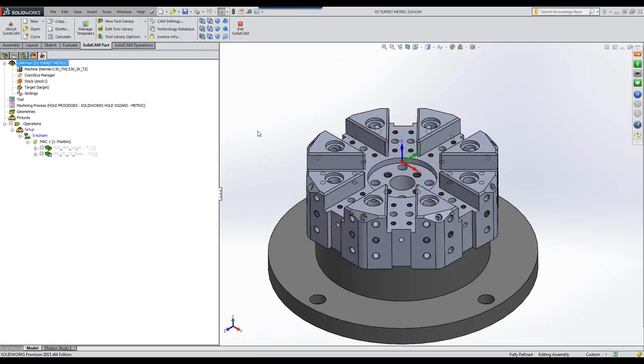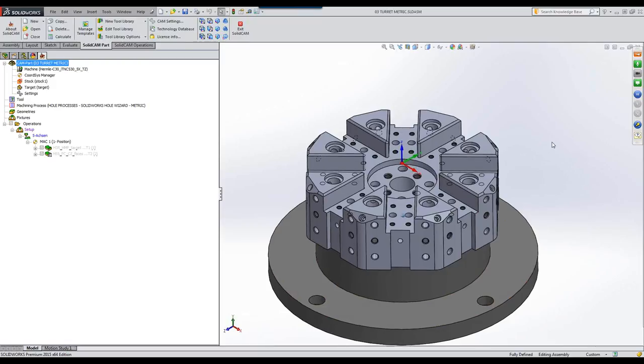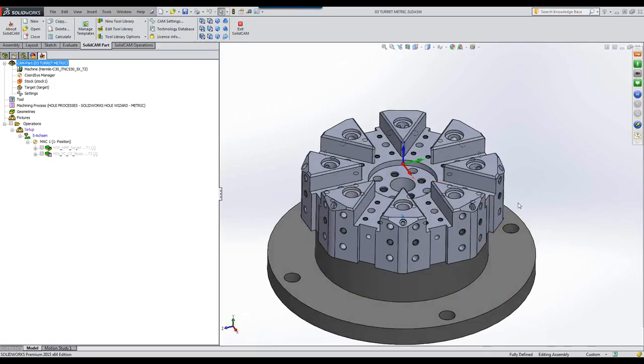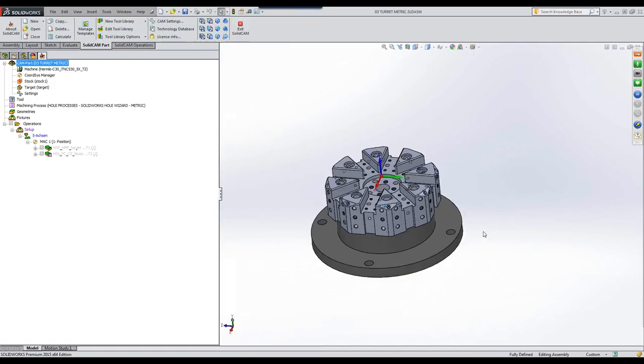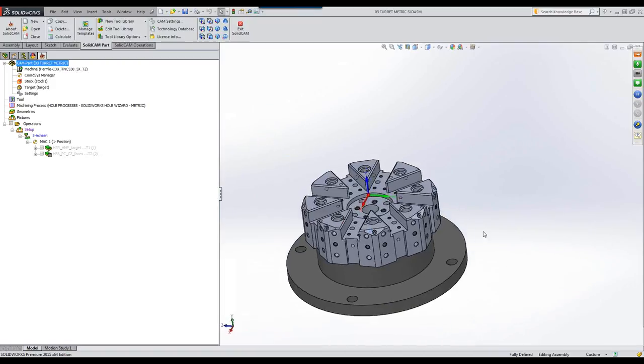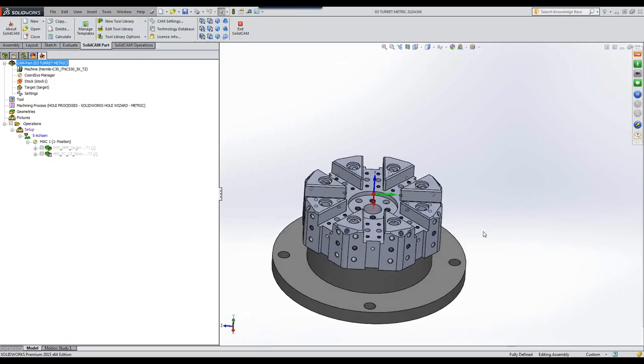Okay, now besides that, I also have multi-sided. In other words, I have to drill out, and even though this machine is a five-axis indexial machine, I would still have to create also home positions for each one of the sides over here, as well as this side over here, even though it's on a multi-axis machine. The home position I still have to create as a different position. Same MAC, different position.